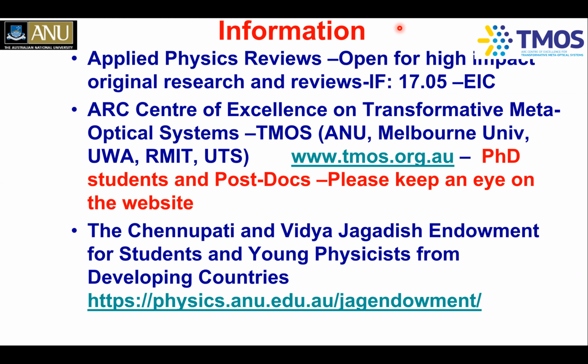Okay, so next is what's your view on 2D material TMDC integrated on nanowire? Oh, that will be very interesting. In fact, it's interesting you asked that question. We are working with my colleagues at RMIT University, where some of the TMDCs are very good P-type materials, and we are trying to put those TMDCs as a P-type contact on these indium phosphide nanowires, and see whether we will be able to get electrically injected lasers or not. So there's a lot of potential of combining nanowires with TMDCs as well.